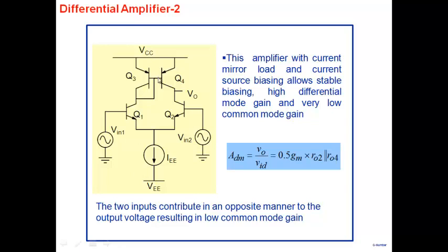If I didn't have this current mirror, if I had an RC here and an RC here, this particular one does not directly affect this particular part. But now because of this, this goes and develops a negative voltage here, this negative comes here and causes a positive voltage, while this one creates a negative here. So because of this cancellation effect, our method of taking values of Norton's currents and Norton resistance and approximating it didn't work very well, because there's a cancellation effect going on, and you have to do the calculation very accurately.